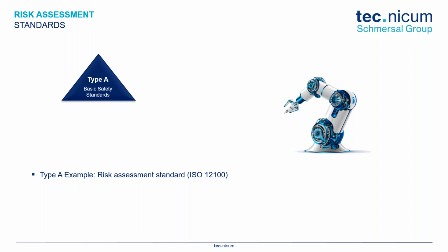What we're going to try to do here is look at this industrial robot from one of our earlier slides, and say, okay, let's try to apply these risk assessment procedures, this process, to this robot. And we know that anytime we see an industrial robot, there's some guarding around, right? Because there's that possibility of fatality. An industrial robot moving at full speed, coming into contact with a human, is going to be rated as a fatality, right? When you go through your risk estimation, okay? So we say, okay, fine.